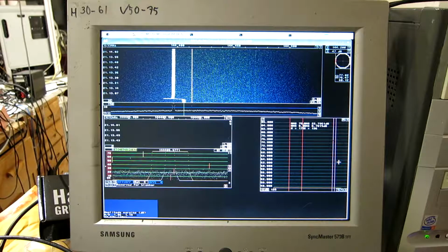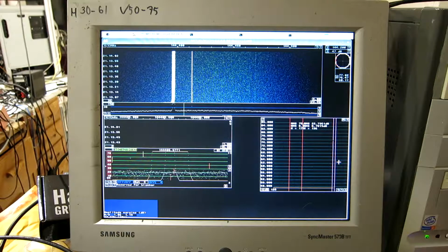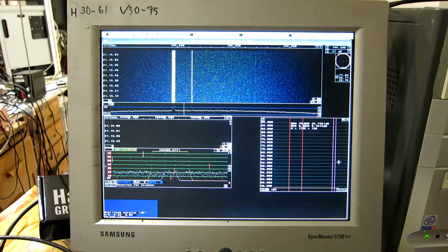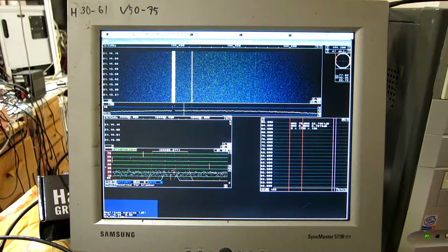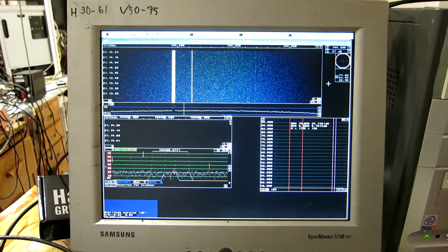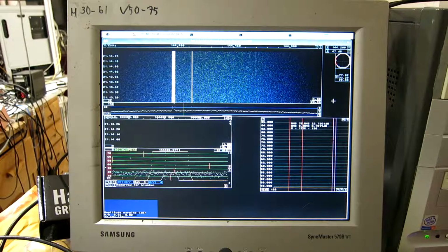And that's where the dongle saturates now, when it is set for maximum sensitivity, which means the gain up here is set to 47 dB. I will now reduce the gain until there is a 1 dB loss of sensitivity, and then look at the dynamic range.